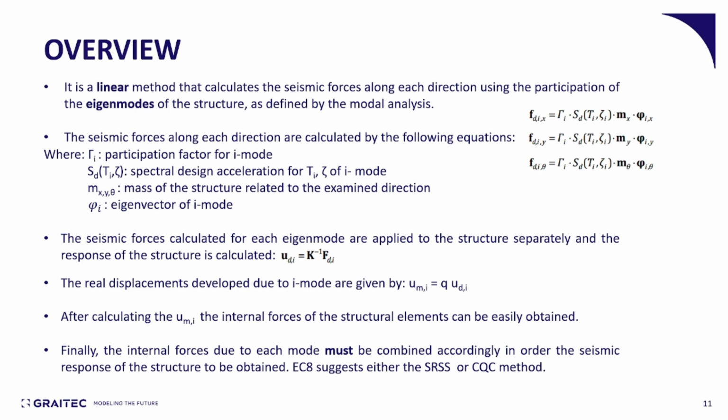And finally, the internal forces due to each mode must be combined accordingly in order for the seismic response of the structure to be obtained. The Eurocode suggests either the SRSS or the CQC method. Either of those can be used, and it's up to the user to know the limitations of the two and select the one that produces the best results. The whole concept behind this is that each mode participates in the total response of the structure. So basically, we need to combine the internal forces in the end in order to get the entire seismic response.